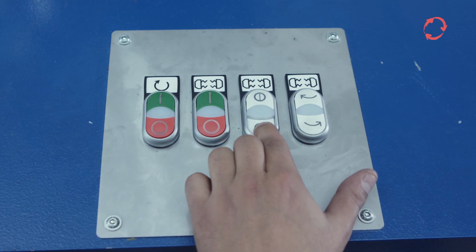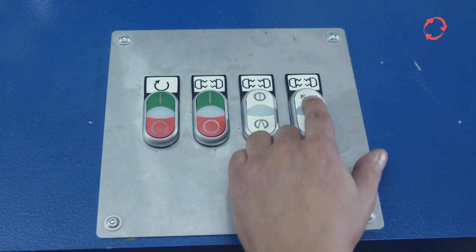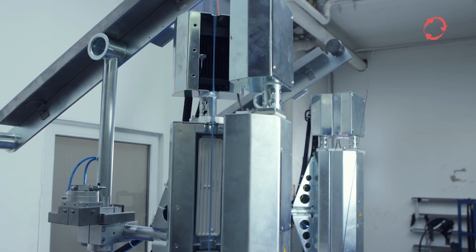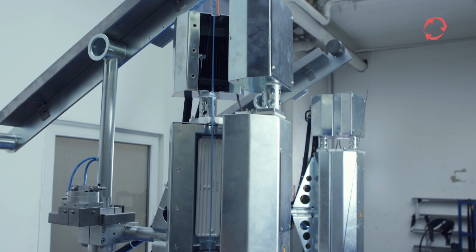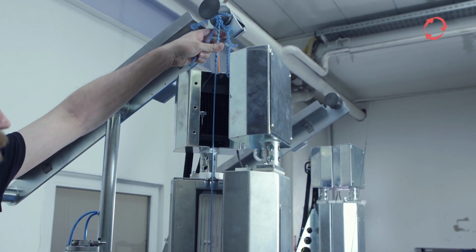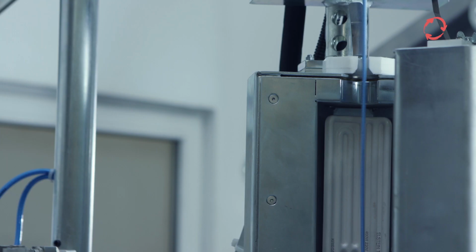Open the heater while the spiral is in the upper position. Now swing the heater to the mandrel using the push buttons. As soon as the wound spiral reaches the top end of the mandrel, the heater is closed by pressing the corresponding button, and the spiral is placed in the downward-sloping guiding track of the machine.